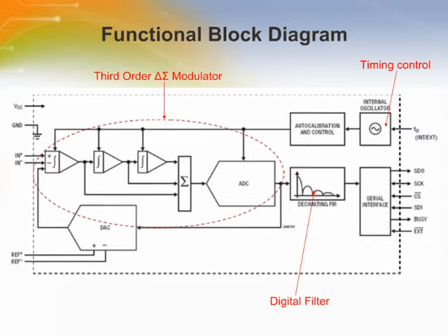The voltage on the differential analog pins can have any value between ground minus 0.3 volts and VCC plus 0.3 volts. Within these limits, the converter bipolar input range extends from negative 0.5 to 0.5 VREF. Outside this range, the converter produces unique overrange and underrange output codes. The LTC2440 can accept a differential reference voltage from 0.1 volts to VCC.